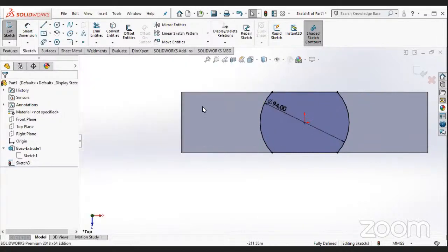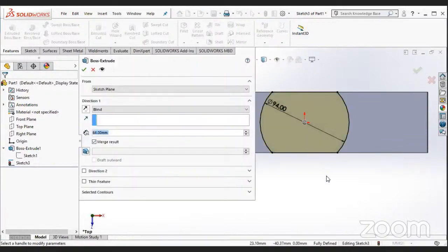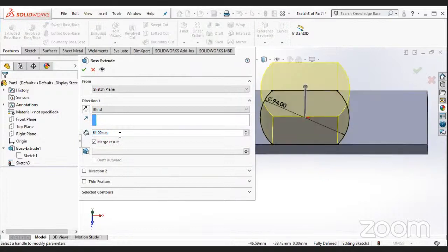Then you can just quickly extrude this, and the height for the extrude as per the given diagram is 63 plus 25, as you can see here, and that is from the bottom, so you have to minus 22 from it, so that will be 66. So we'll quickly extrude that to 66 height. It is already 64. We'll make it 66.